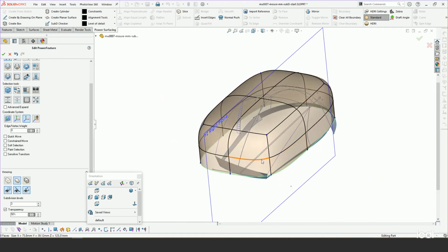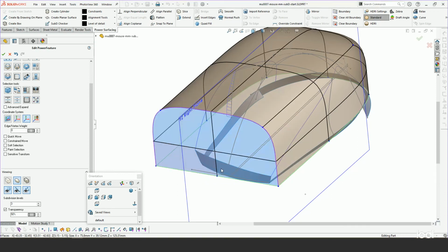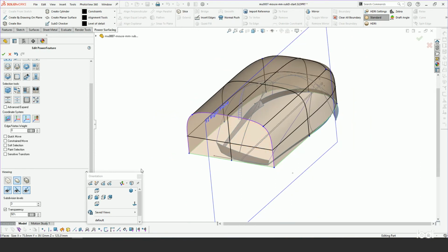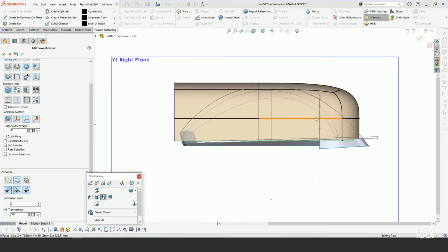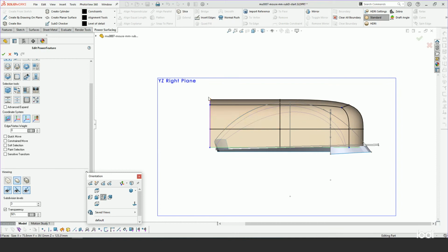And then on the front, it has a rather hard edge in the front of the mouse, so I'm going to select these four faces, and I'm just going to put a crease in those edges so that there's a hard crease. Let's reshape it a little bit, maybe divide it to get it closer to these edges that I'm going to eventually align it to. So we're going to just start working to move this around, and I'll probably speed the video up at this point just so you don't have to wait for me to make decisions, and you can see this a little quicker.